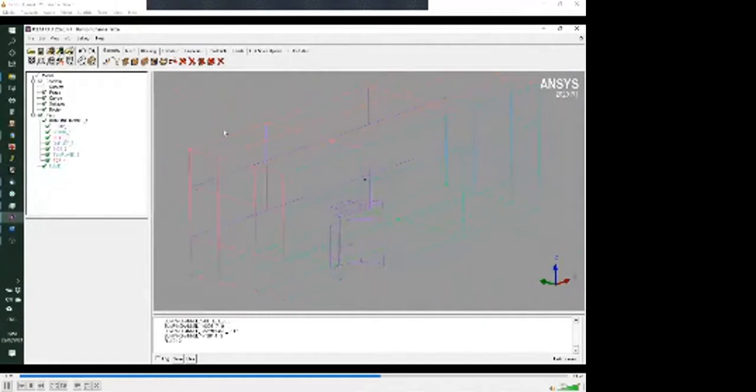When you're doing unstructured meshing like this, it's really important to make sure that your model is watertight. The structured meshing is less concerned about that. It will tend to skip over small bumps or holes in the model. But an unstructured mesh will very often leak. It will leak grid cells through a region where there are, for example, holes, or even worse, where there are overlaps.